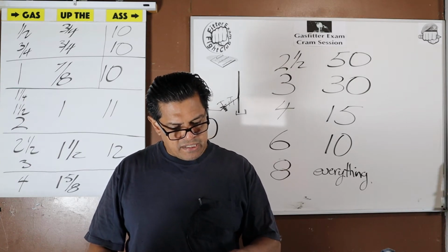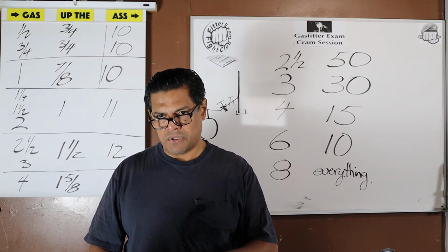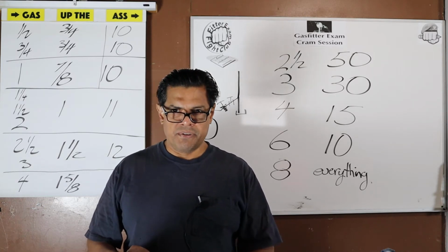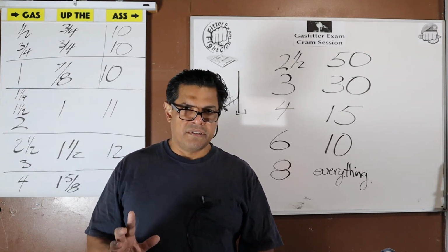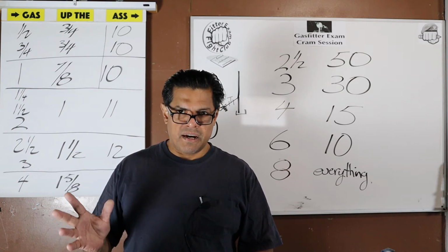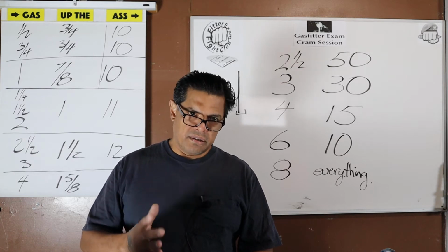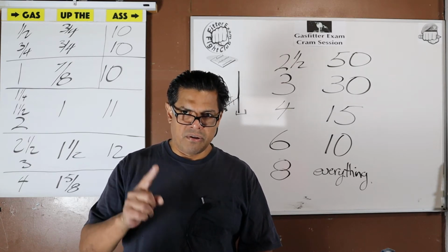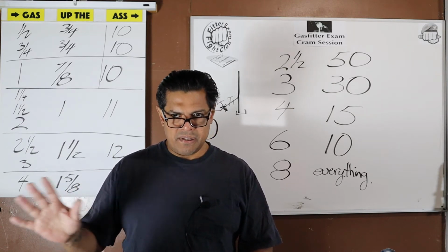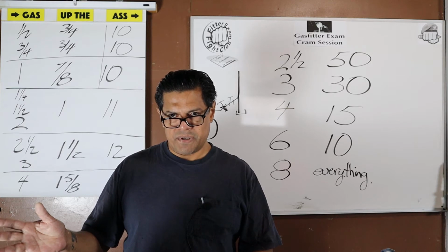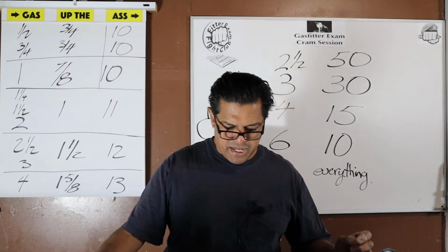And in this case, the exception is for commercial, industrial, and other large volume use. So, maybe a residential building is not commercial, industrial, but if it's an apartment complex, if this is a huge high-rise, the boilers are going to be pretty huge. They're going to require a great amount of gas, large volume use. That line may be over half a psi. It'll be in the half to 5 psi range. Okay? Maybe, possible.